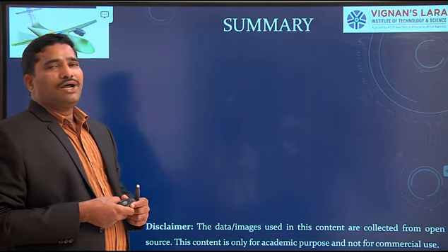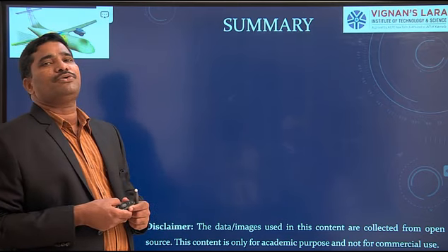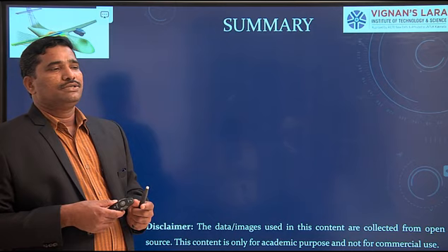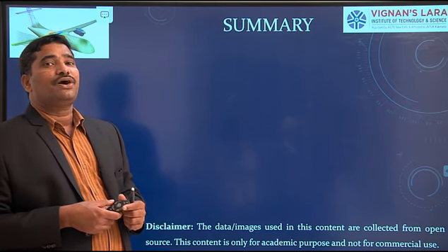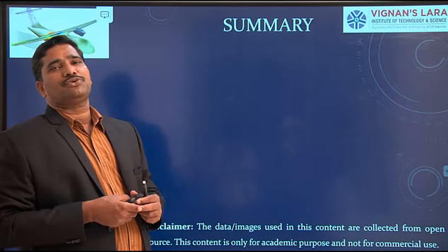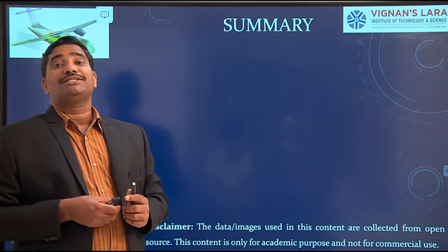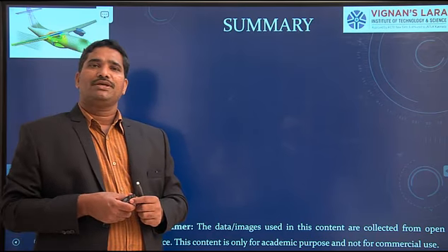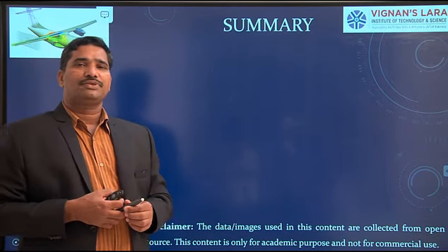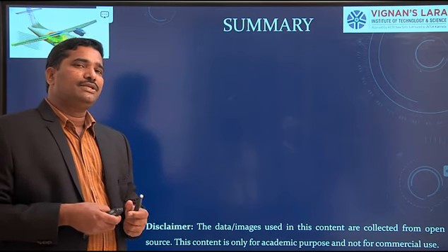Right? So the Rayleigh-Ritz method says you have to choose an admissible function satisfying the governing differential equation and boundary conditions. Then we have to determine the total potential energy. Remember, the admissible function we choose contains a set of arbitrary constants. Therefore, after determining the total potential energy, we differentiate it with respect to each constant. Then we get a set of algebraic equations equal to the number of constants. Then we solve them to get the values of the arbitrary constants. We substitute in the respective equations. Then we get the solution for the given problem.